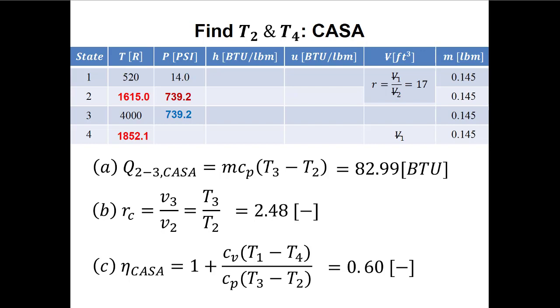And that's it for diesel cycles. So hopefully, through these 3 lectures, you've got a good idea of how to tackle these internal combustion engine problems. Essentially, what we need to remember is that internal combustion engines are heat engines. So we characterize them all as being the net power, or the net work, divided by the heat transfer rate in, or the heat in.